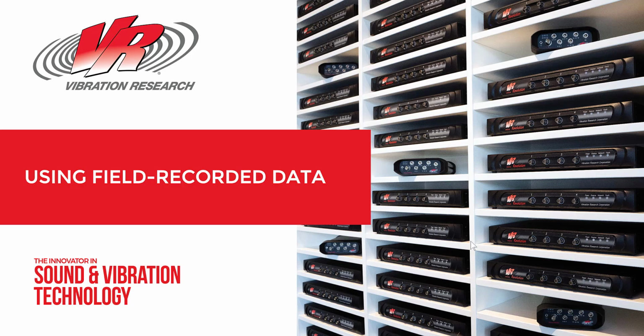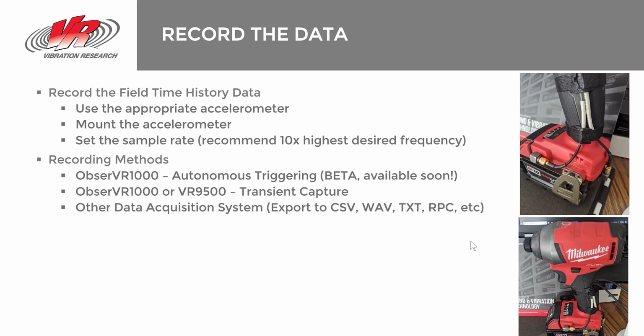So now we're going to talk about the application. Today I have a Milwaukee drill. It's an impact drill. I have one accelerometer mounted on the frame of the drill right where the battery would mount, and I have another one that is mounted to the back of the battery. And we are going to record that environment.